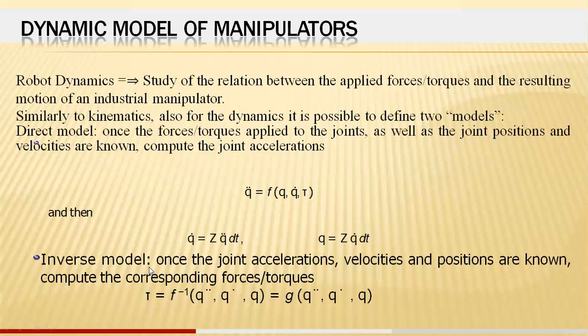So for example, at a 0, 0, 0 point, which is the origin point, the end effector starts. On the basis of its link 1, it rotates 30 degrees, and link 2 again rotates 30 degrees. And finally, link 3 is sliding. Particularly, it will be achieved and exist within the XY coordinate frame only.